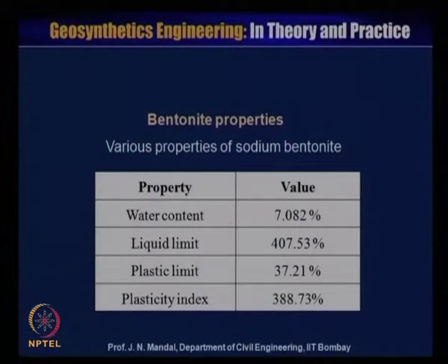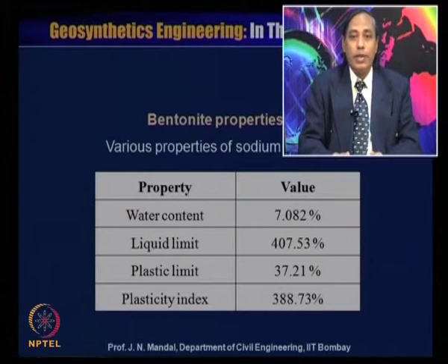Before going through the test procedure, we would like to focus on what the properties of the bentonite should be. These are various properties of the sodium bentonite. It contains water content 7.082 percent, liquid limit 407.53 percent, plastic limit 37.21 percent, plasticity index 388.73 percent.